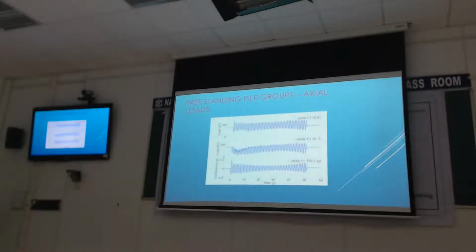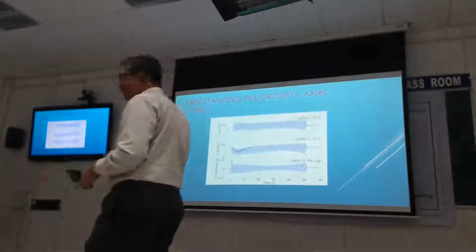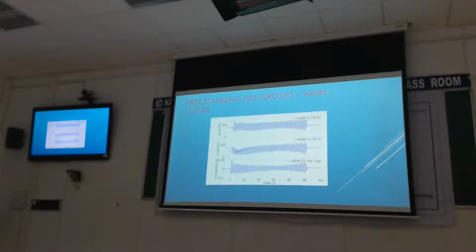And, okay, you do the earthquake. We applied a fairly large earthquake, 0.2 g, shaken for quite a lot of cycles. And these are the loads measured at the top and bottom strain gauges. These are measuring vertical loads, right? So you can see that they're getting up to about 500 kilonewtons, about 50 tons in prototype scale, in each one. So these are quite a lot of load, as I said.